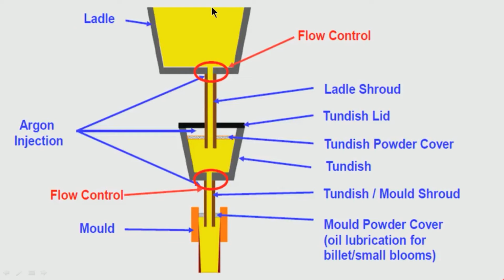So, we should not allow the slag to come down after the liquid steel and get into the tundish, because slag is an exogenous constituent, basically oxides. Liquid steel is liquid steel, it is steel. So, we do not want slag to get into the tundish, entrained into the liquid steel. We have to stop the slag from getting into the tundish. So, what do we do for that? How do you know when slag will come?